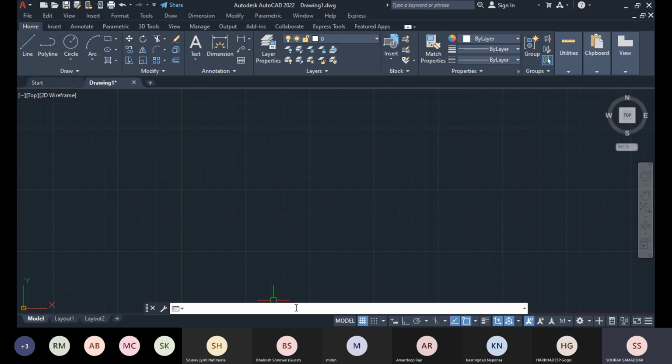So how to use this method? The main methodology is that you have to count all coordinate values of your drawing from the origin point, and that's why this method is known as the absolute coordinate system.